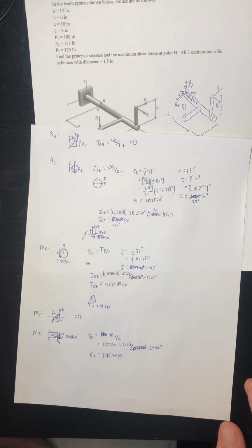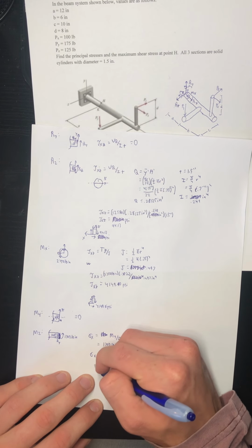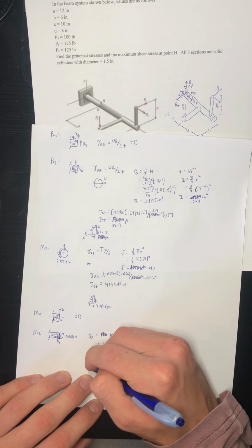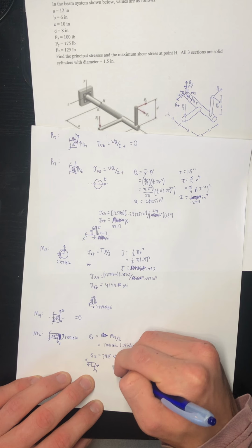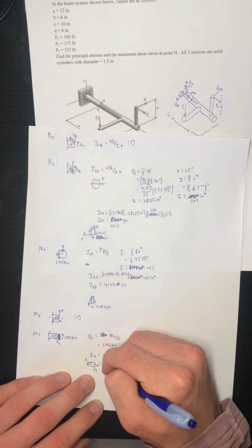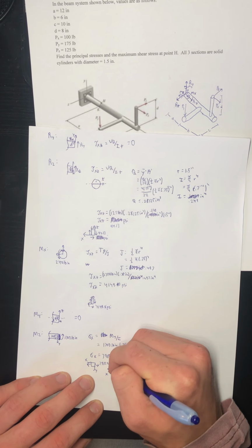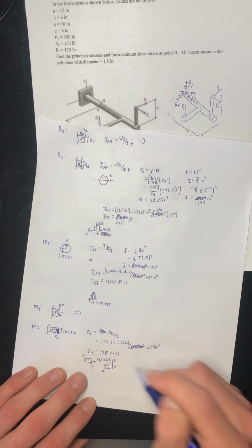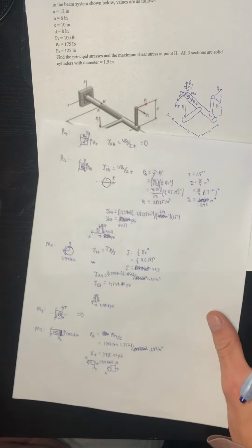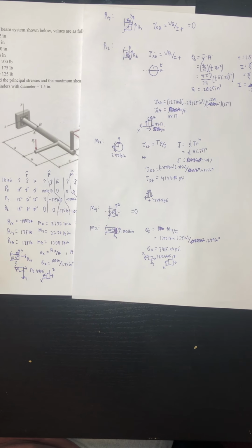Okay, so we now have all of our stresses, and I can go ahead and put this on the stress block as well. We have going on in that direction, and we also have Z and X in this direction. That's 3,915.66 psi in tension. So now we need to go ahead and superimpose all of our sets of stress blocks together.